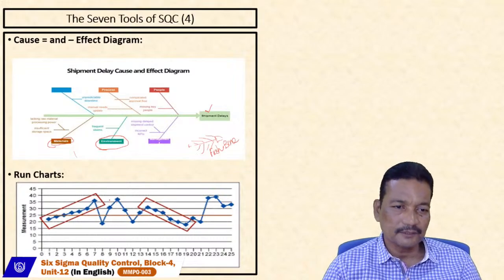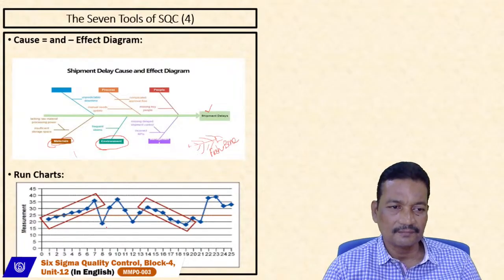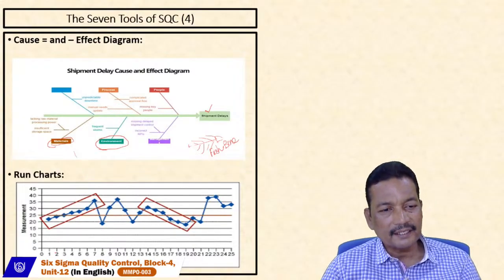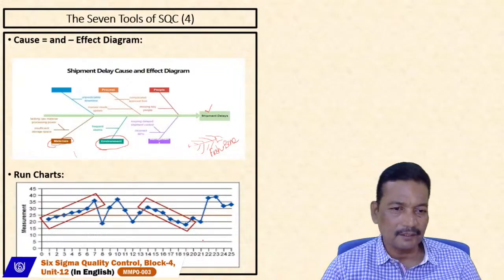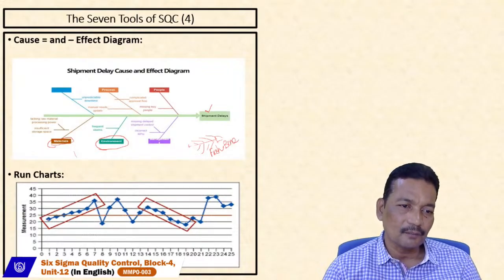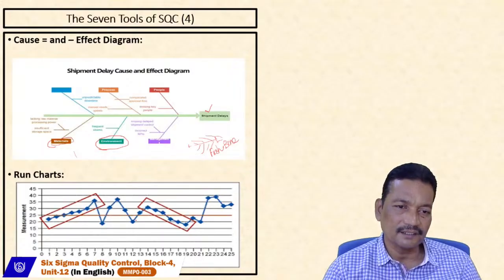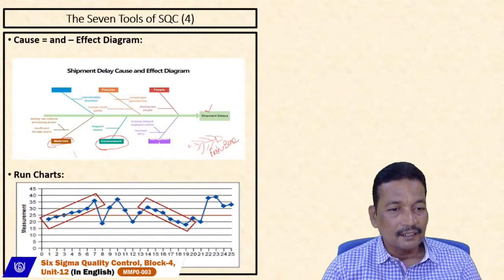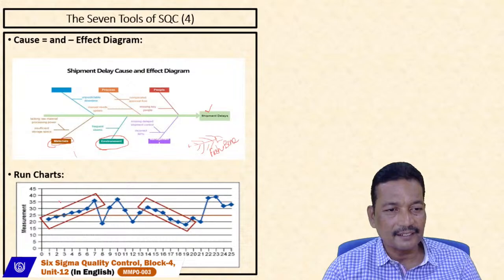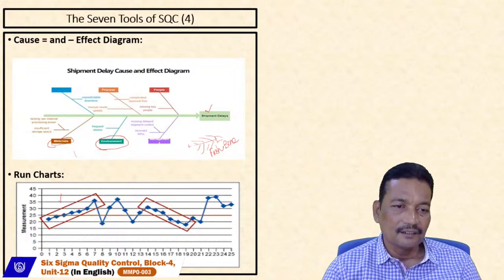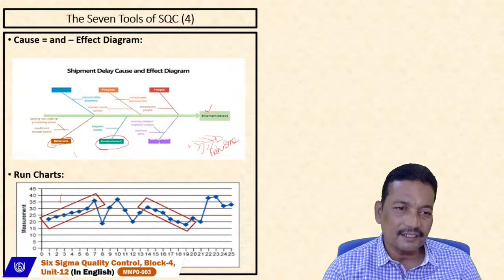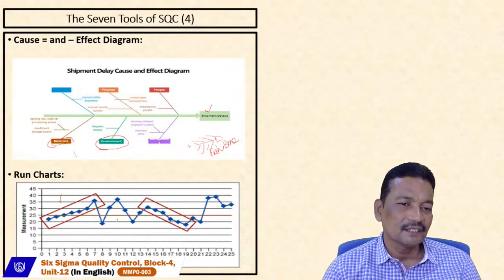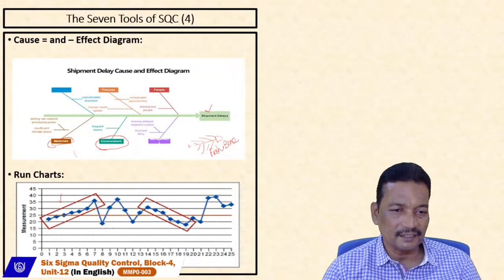Another important tool of statistical quality control is runs or run chart. Now, we take a continuous measurement of the items that are being produced and plot the measurement on a graph on a continuous basis. Here it has been marked as red. What is the general trend here? Now it is moving upwards. Here we cannot get any trends because only one or 2 points are there.